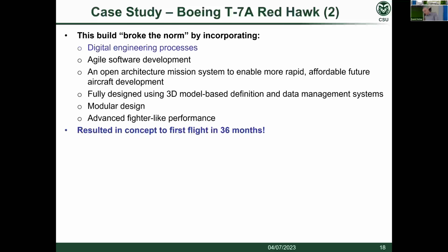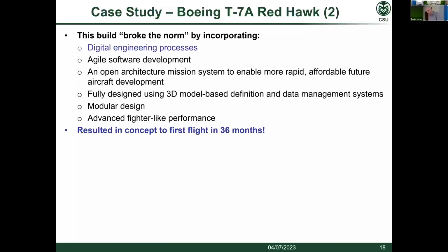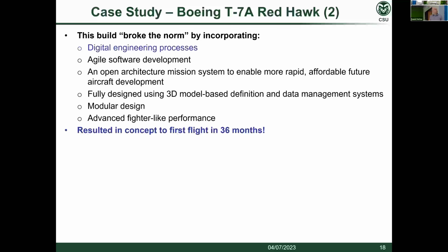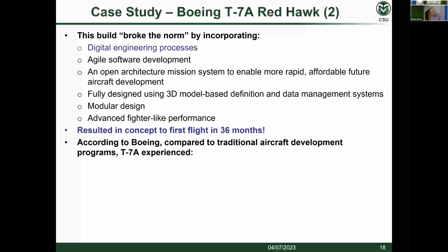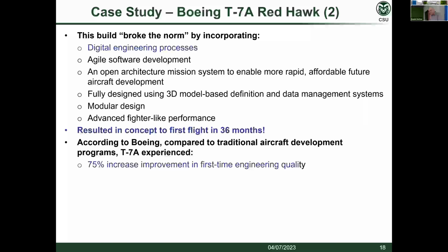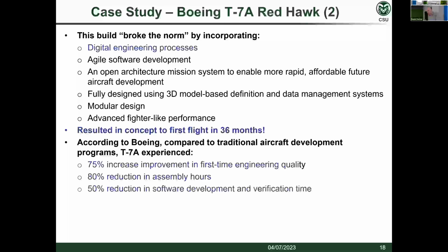So the result of embracing not just digital engineering, but more broadly, these other more cutting-edge approaches to system development, was a much shorter concept-to-first-flight time of only 36 months here. Now, we can quantify some other things. According to Boeing, compared to a more traditional aircraft development program, this particular program experienced a 75% increase in first-time engineering quality, fewer errors, things like that, an 80% reduction in assembly hours, as well as a 50% reduction in software development and verification time.